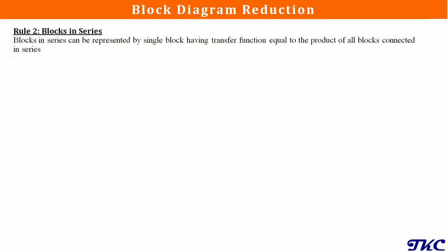Now the next rule we have is blocks in series. This rule says that when we have a number of blocks in series, we can replace all those blocks with a single block that has an equivalent transfer function, which will be a multiplication of all those blocks.